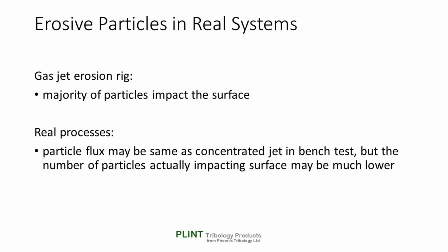Modelling the particle properties, concentration and velocities in a real flow system is a complex CFD problem, especially when it comes to modelling the behaviour of particles in the boundary layer, where drag forces may have the tendency to slow the particles down before they reach the surface.